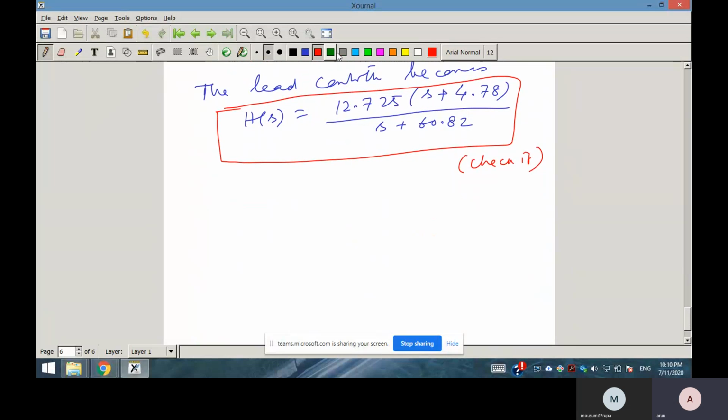So now the lead controller design is over. Now, as I said, given the phase margin specification and steady state error specification, you can design lag, lead, all three controllers. But your omega c will be different. Omega c here I have chosen higher. Now you will see that for lag controller design omega c has to be less, so the system will become slow. You can get the same phase margin specification, but here the gain curve has to be lowered down.